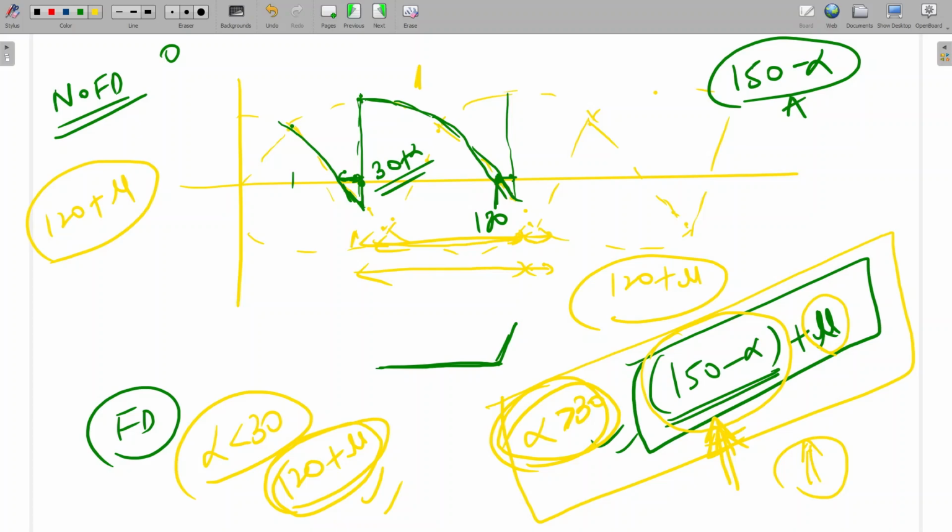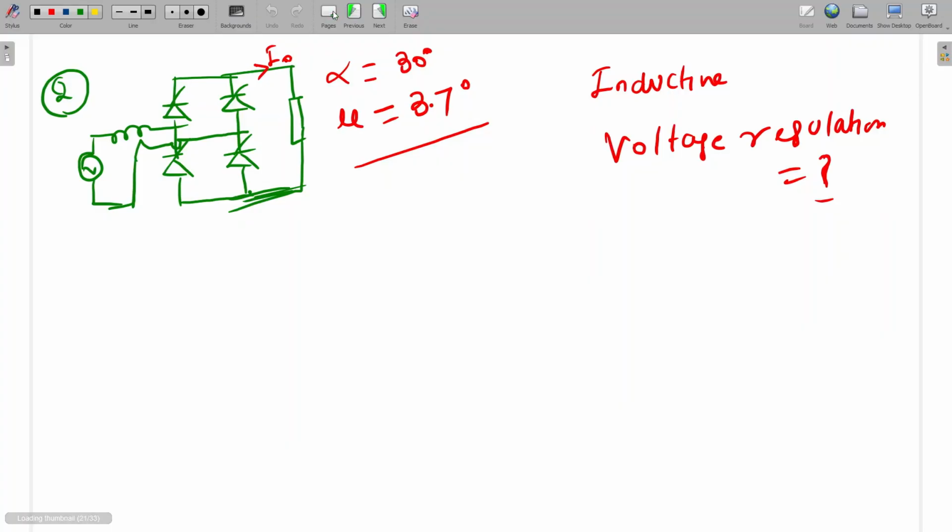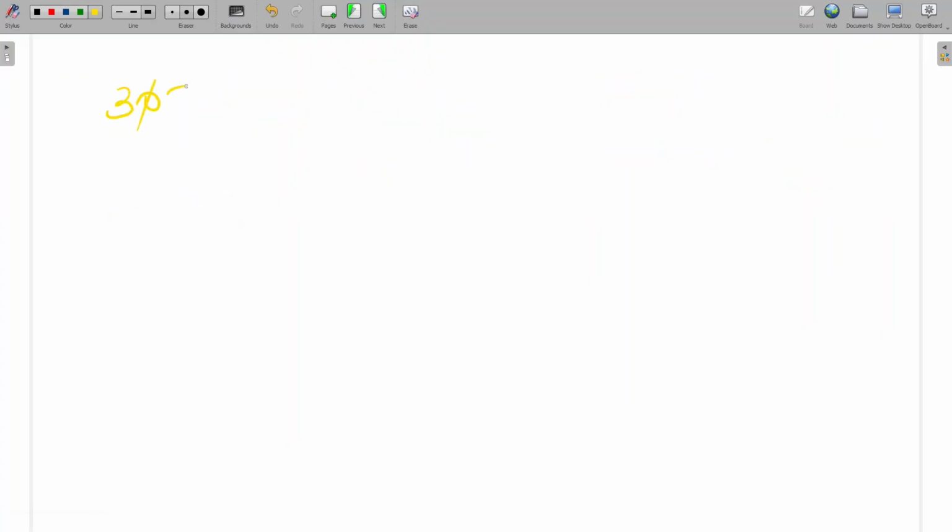But the three-phase full wave is also the same, sir. For three-phase full wave, that analysis I have done. In the next class I will draw that waveform, then it will be more clear. That is also normally conducting for 120 degree, the three-phase full bridge.